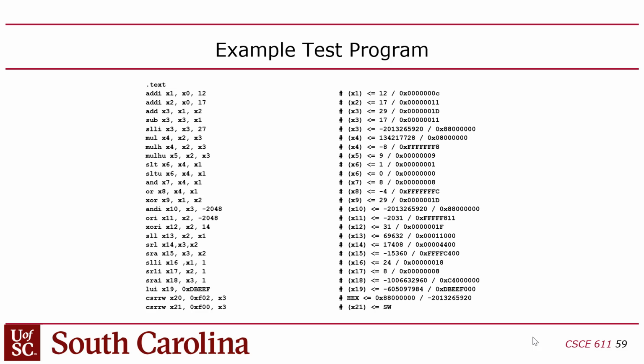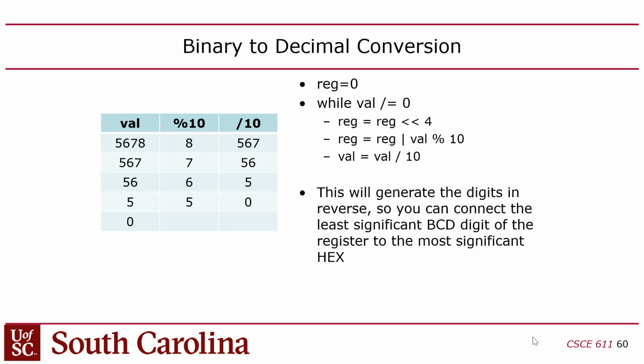Yes. So this doesn't have any dependencies that would require stalls in the pipeline? No, stalls are just, we're going to need those for the branches. But this won't need that. No. Yeah, we don't have the ability to stall. One thing I've wanted to do is to add a multi-cycle divide instruction in here where if you have a divide instruction, it would stall in order to give the divide time to work. But we haven't done that yet. But that would be an example, like if you have a multi-cycle instruction, you would need to stall for that.